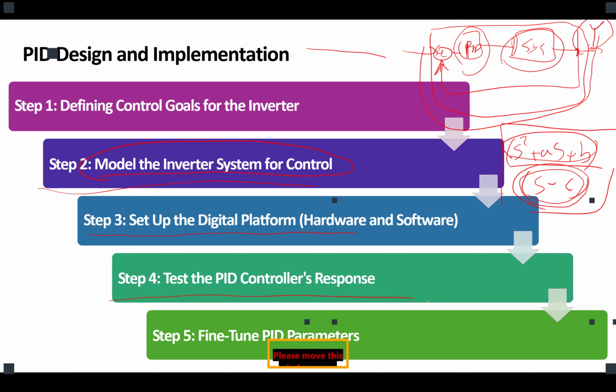After you test it, you are going to see how it reacts compared to how you want the PID to react. Say you want a certain level of overshoot that you accept, and you see it has a higher overshoot than you want. So what to do? We go back and play with KD to get rid of that. We look at the output in testing, and we see there's still a residual error more than what we allowed the system to have.